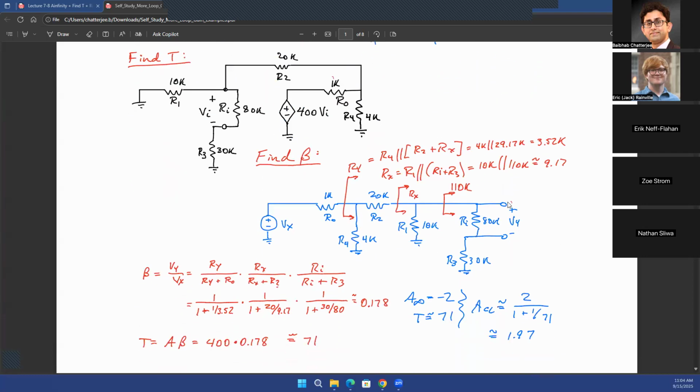So basically the voltage that you're looking at, over here the way it is drawn, it has to be the opposite. I can correct this slide and re-upload, but that's a great point that this needs to be the positive terminal and this is the negative terminal if you want to be perfectly accurate. So basically this is going to be negative and this is going to be positive. But then again, think about it: we are looking at the absolute value of the gain in most cases that you have seen. So the absolute value of the gain does not change. But because it is flipped, you're right that if you want to be exactly accurate, there would be a 180-degree phase shift because of the feedback, right?